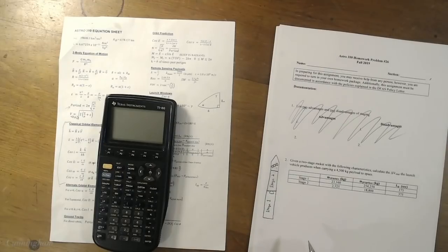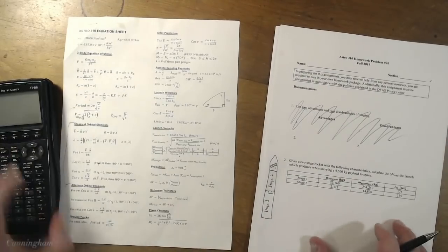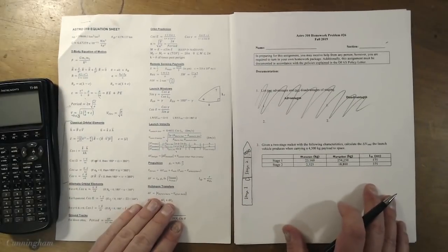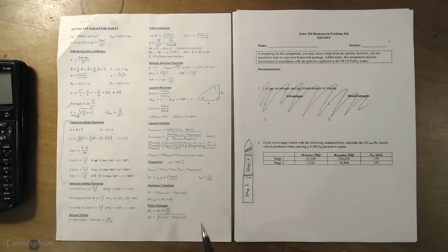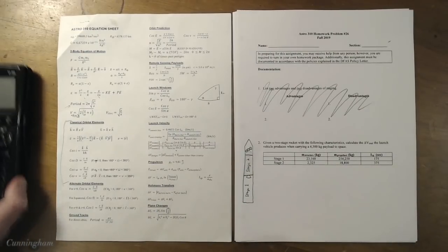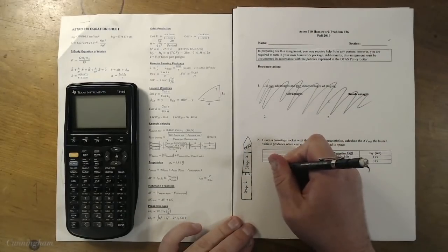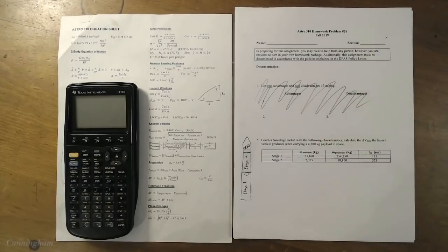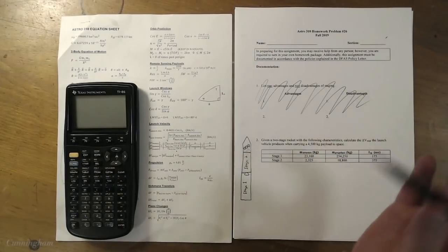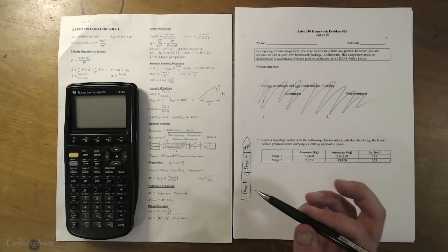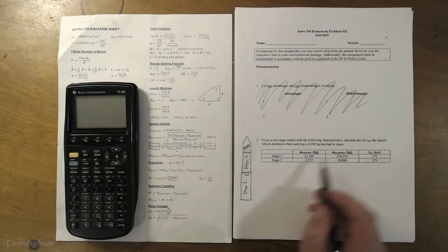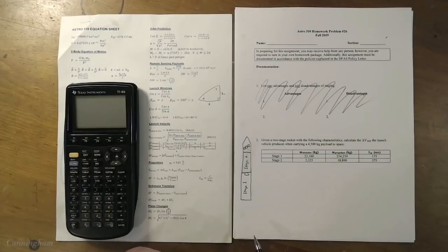Cool. Where you make your money with this is the ideal rocket equation. That's on the front page of your equation sheet, down near the bottom right, next to Hohmann transfers. Remember life back when we were just doing Hohmann transfers? Life was so good. Well, life is still good, but we're going to use the ideal rocket equation to say how much rocket oomph we need for each stage to get our huge satellite out to space. That's pretty tough, but it's doable, and we do it all the time.